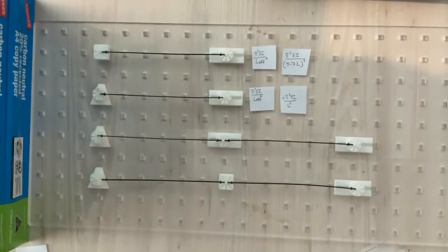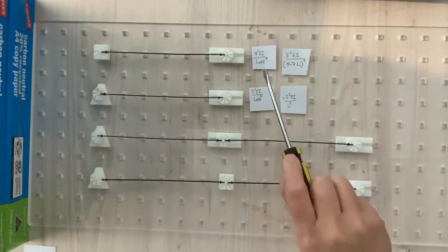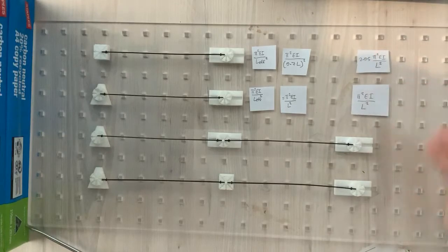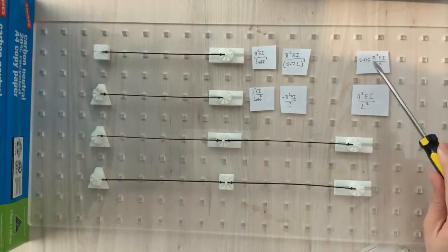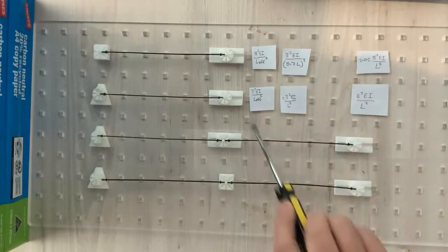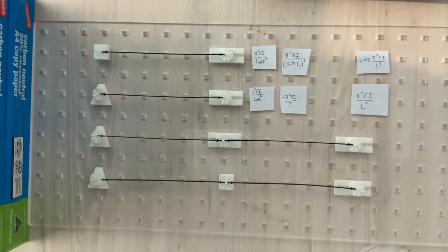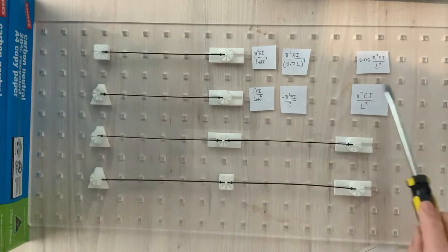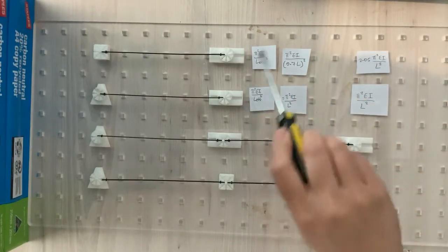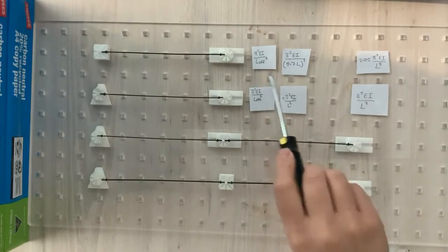So when engineers think about these things, there's two ways to think about it. One of them is through an effective length concept, and the other way is to think of it through the changes to the pi squared EI over L squared, that this one here is 2.05 times larger. Both ways are completely consistent, so you'll be able to convert from here to here quite easily. But generally, when engineers talk, we're talking in terms of effective length.